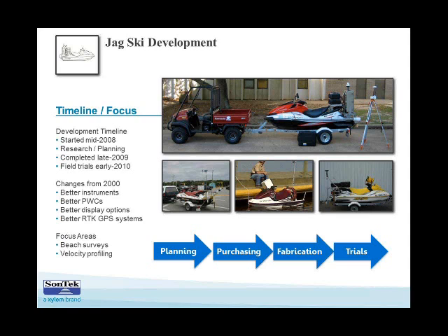So we repeated those transects a number of times throughout the day, kind of hopping from place to place. There's a different river that's further to the east. And we used all this information, the bathymetric mapping, the discharge and velocity measurements, to set up and validate and calibrate the circulation model that we could then use to run the alternative restoration simulations. So it's a neat project. It's a lot of different aspects all lumped into one, and it really provided a complete solution, or turnkey solution I should say, to go out and do everything we needed to do.